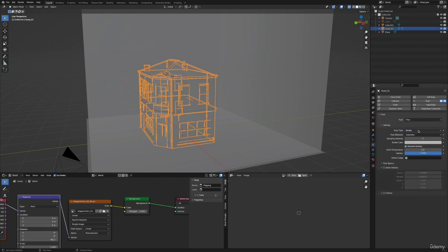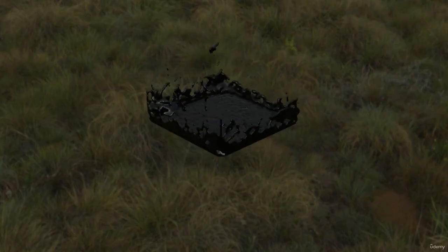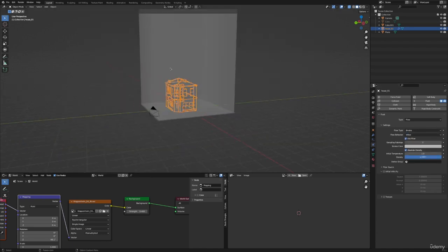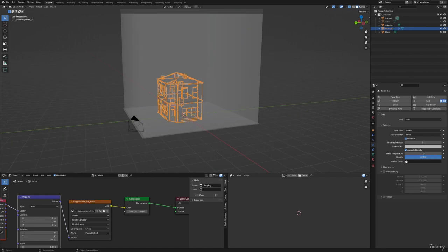We do flow behavior, and it should not be geometry, but it should be inflow. This is the same as what we did in the liquid simulation, because geometry is sort of a one-time use of particles of a certain kind. Like in this case, for example, the smoke would then take the shape of the geometry. It's kind of like what we did with the liquid simulation, where the liquid became the bottom. Remember that? Well, here the same would happen with the smoke. We don't want that. We want inflow so that it keeps flowing out continuously, and there's a continuous flow from our object into our domain, because that is how realistic smoke would work.